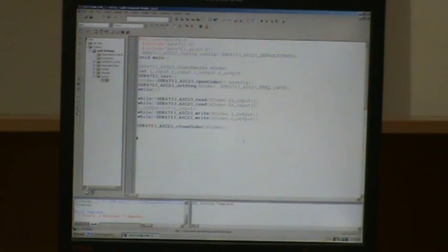Here we are talking about generating a signal of 4 kilohertz, a 4 kilohertz sine wave with 200 millivolt peak-to-peak, using the function generator. The function generator is used to generate the external signal. So for this purpose we have to connect the function generator to Line In. Line In means line input, and then write the code.